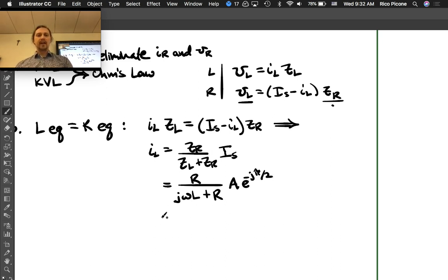So we can simplify that, right? There are two ways to go here. We could turn the denominator into a phasor because we're going to divide, or you could do the complex conjugate thing to rationalize that complex fraction. It's up to you. Let's do the phasor one, just because that's good practice. So let's turn the denominator into a phasor. The numerator will also turn into a phasor because we're going to divide.